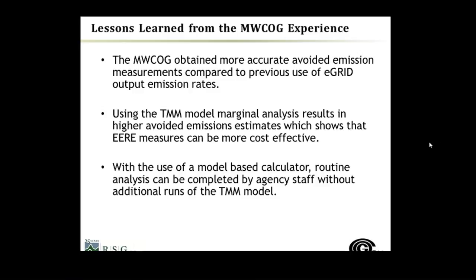We create the hourly generation data for all the fossil fuel units by taking the CO2 emissions from the continuous emissions monitoring data, and then with the use of an appropriate emission factor for CO2 per megawatt hour based on heat rate and so on, we can get a very close match for the hourly generation of all the fossil fuel units. And the non-fossil fuel units are in general not relevant to this analysis.